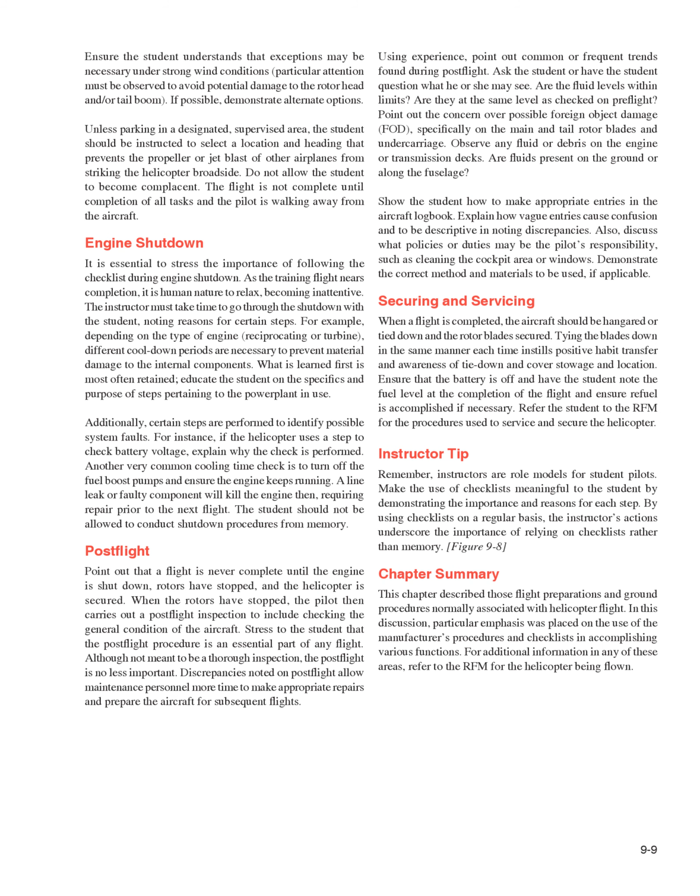Engine shutdown. It is essential to stress the importance of following the checklist during engine shutdown. As the training flight nears completion, it is human nature to relax, becoming inattentive. The instructor must take time to go through the shutdown with the student, noting reasons for certain steps. For example, depending on the type of engine, reciprocating or turbine, different cool-down periods are necessary to prevent material damage to the internal components. What is learned first is most often retained.